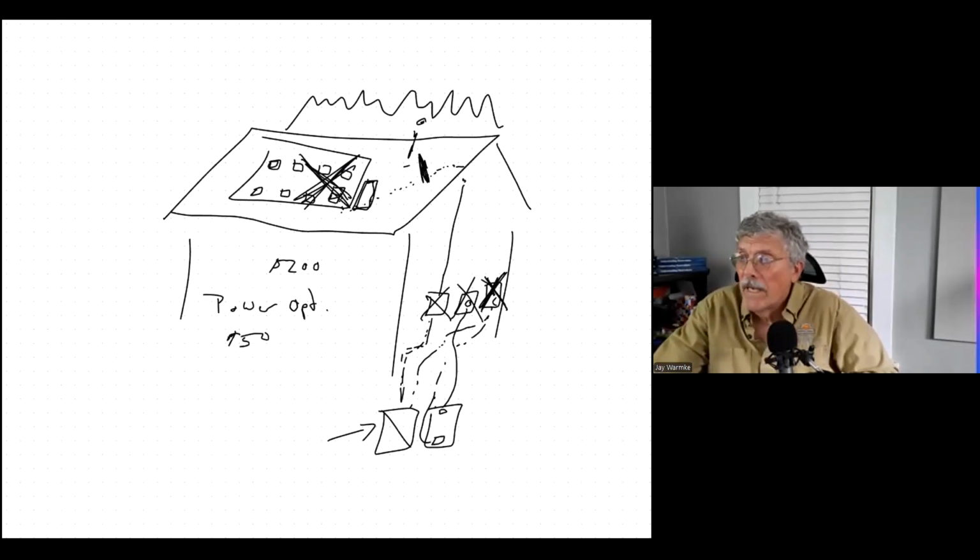So what ended up happening is in the residential marketplace in the US, microinverters and power optimizers soon came to dominate the whole world of residential solar. And it was solely because we needed to shut off the power at the array when the first responders come to deal with an emergency. So now optimizers and microinverters represent about 90% of the residential market. But this was a response to a regulation that no one knew how to respond to.